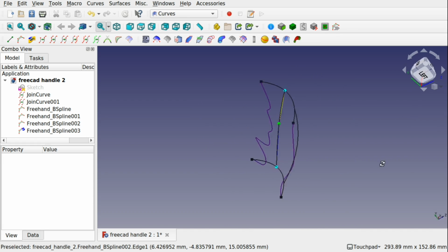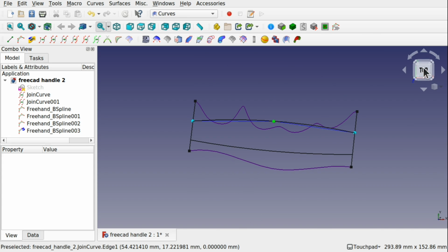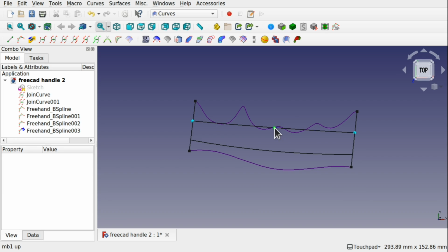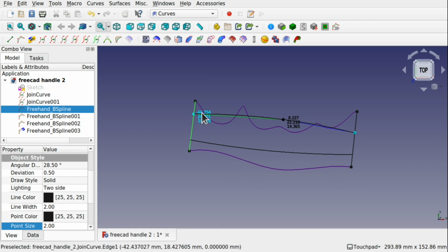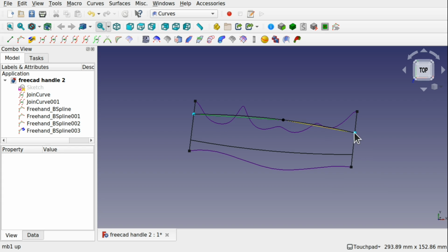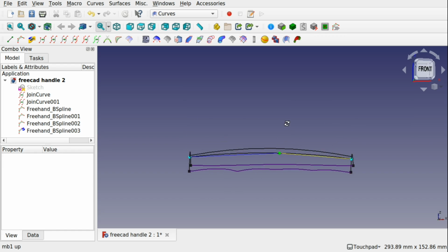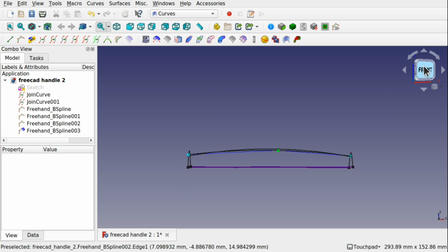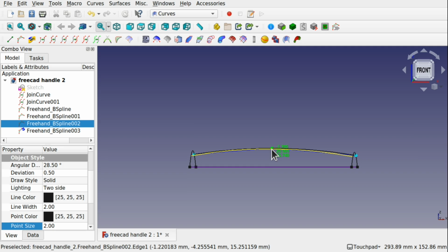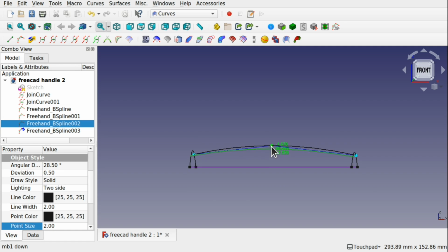And it's moved because I moved the view whilst actually moving this and didn't actually constrain myself to an axis. So I'm just going to move that down, and we'll move these down as well. Come around to the side, and we can control that curvature there. So front, and we'll have some curvature. Just going to match that line. We're just going to hit escape. That places it there.